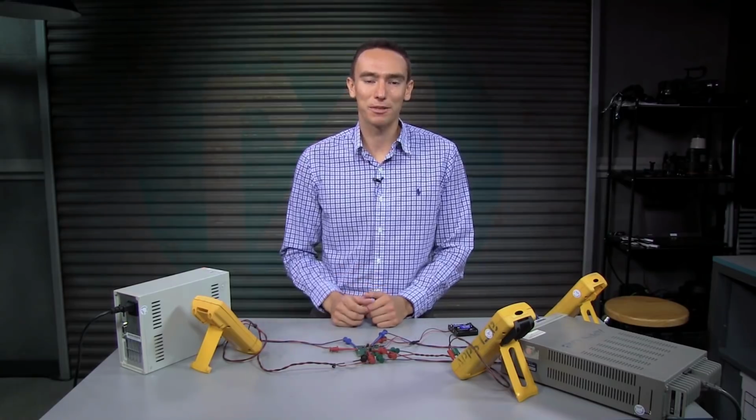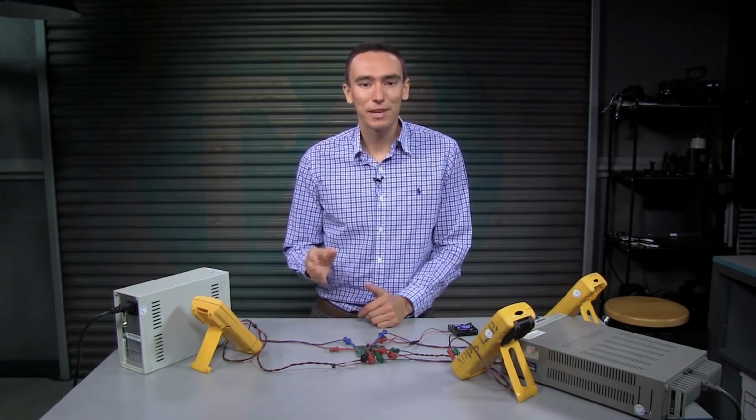I get several customer questions asking whether the second ideal diode, the one in the path of the external power supply, is really necessary, as it will reverse bias the one connected to the battery. While this may seem like a good way to save cost or space, it really depends on external components and the layout of your system. If there are any parasitics or energy storage elements in your circuit that could cause reverse current into the power supply, that could cause damage. Now, I always lean towards safety and keep that second MAX40200, because safety never takes a vacation.